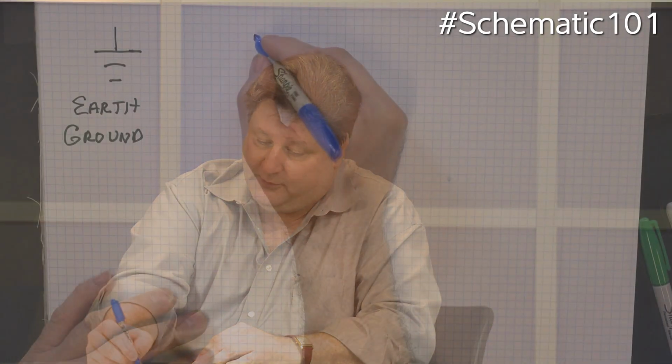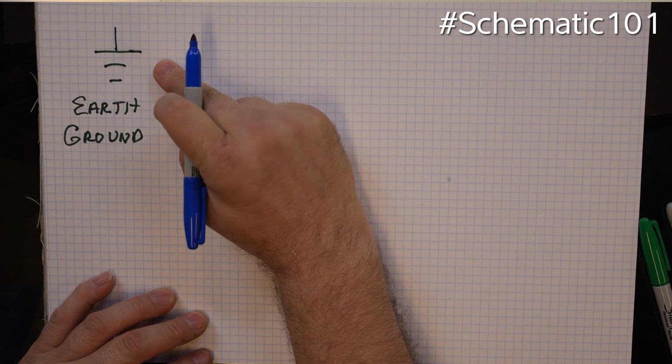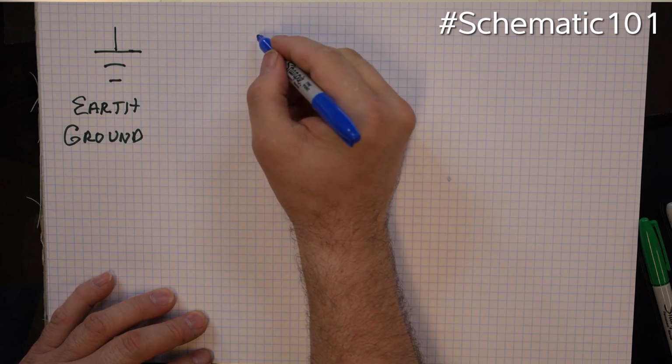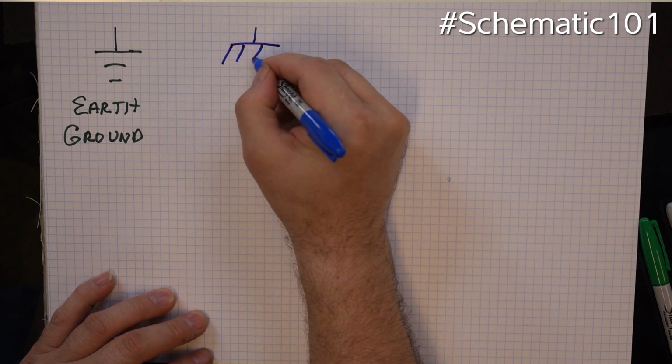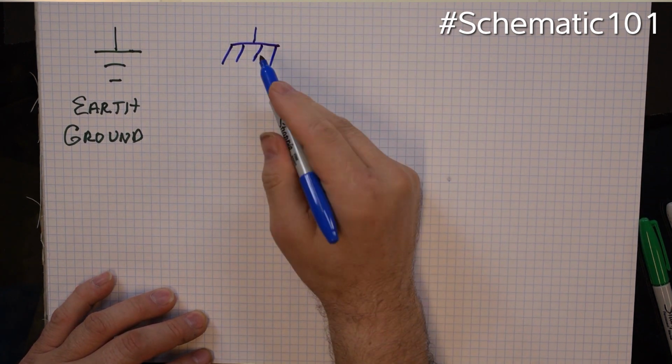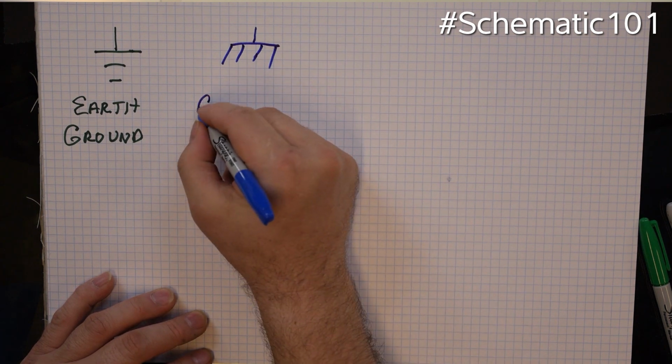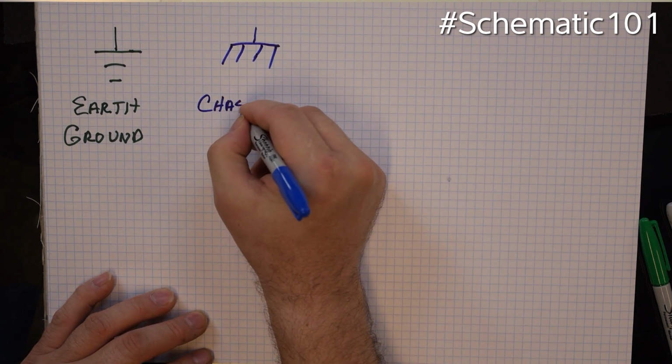The same professor I had, James T. McLaughlin, he would flunk you for the whole semester because we were doing mostly car electronics. If you used this ground symbol on a schematic, sorry, a car isn't grounded, it has rubber tires. What you want to use is this symbol, which is chassis common.